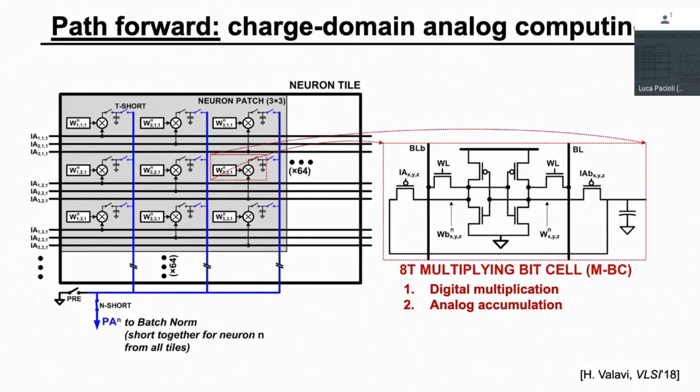Now, this 1-bit output, because it's a binary output, is perfectly linear. You can perfectly fit a line to these 2 points. Okay? But what I'm now going to do is I've stored this as charge, an analog quantity, although it's binary here, on this capacitor. Now to do the accumulation, so this is multiplied. To do the accumulation, I'm going to short these capacitors together, and that's going to give me my accumulation. So the accumulation, which remember is what actually gives me the amortization that I'm going for, is done in this charge domain.